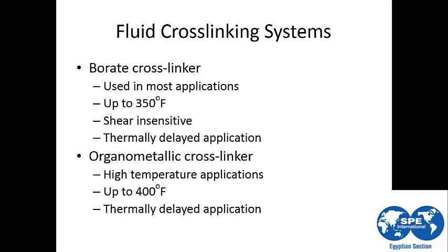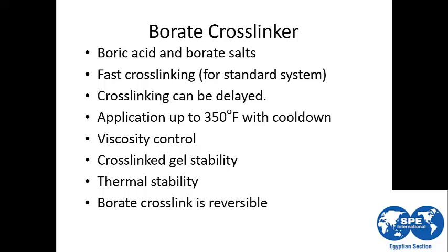But the organometallic crosslinker is sensitive to shear, which means that once it loses viscosity due to increasing shear force, it does not return to its original value. So this is the limitation of the organometallic crosslinker. For the Borate crosslinker, we can add the boron using either boric acid or borate salts.